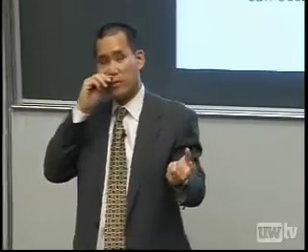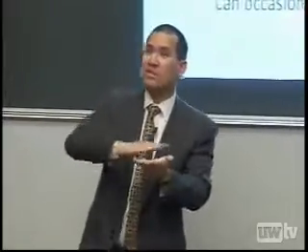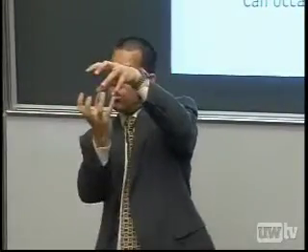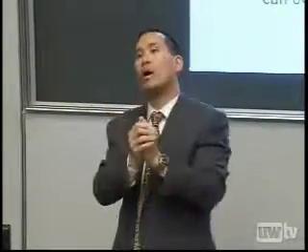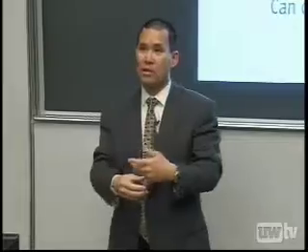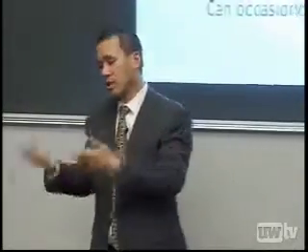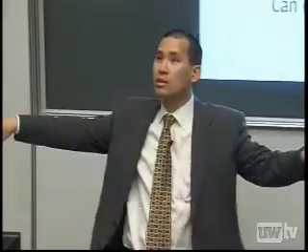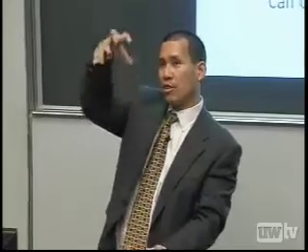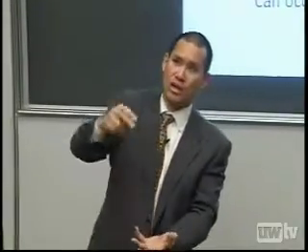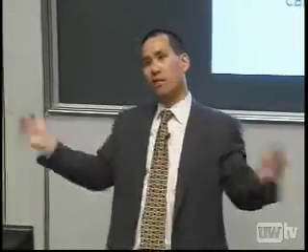One thing the folks in Japan do is thin the chips down so that the so-called aspect ratio, the difference between the loops versus the loop size, is relatively small. It's like a factor of 1. So for certain applications, inductive coupling makes a lot of sense. For what I'm doing, I'd rather go out. I think building up is tough because it's hard to get thermal solutions solved. How do you get the current in and how do you get the heat out? I'd rather build out, and for those applications, I think capacitive coupling makes more sense. But there's a nice interplay there.